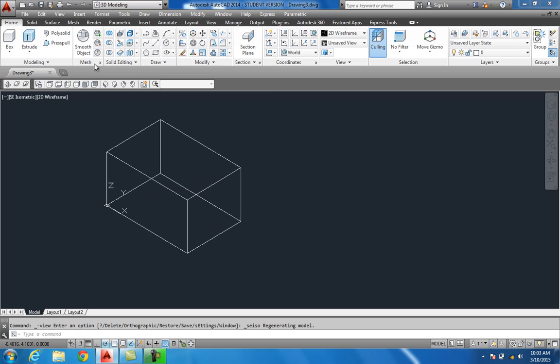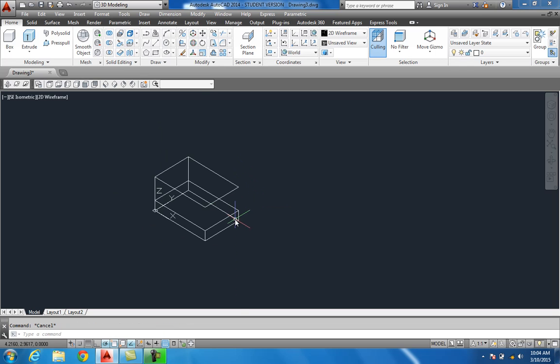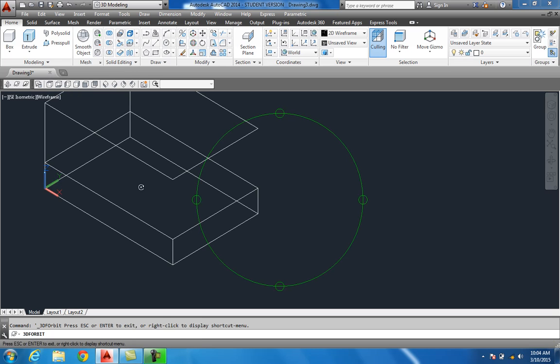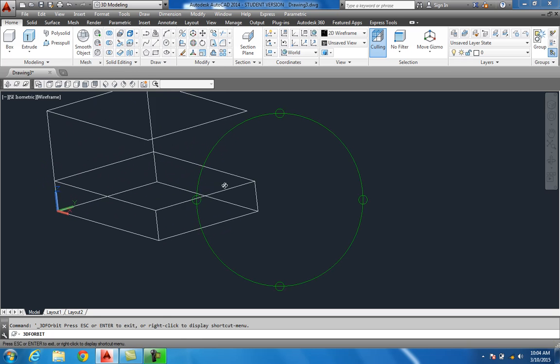Now again, I want to do another copy. I want to bring this whole level up at 0, 0, I want to bring it up 0.75 to make the flange on it. So we've got that in there. Looking good. I want to go ahead and take this and bring that down. Go ahead and bring this one here. Grab the grip and bring it down there. So that's looking good. Check it. Kind of give yourself a look view at it. Make sure nothing's skewed. Looks good.